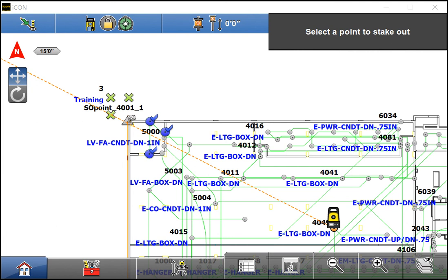Even if you don't need to send the points right away, I typically always export my points and paste them into a folder within the data folder after completing each floor. Name the folder so that you will know it contains your digital records and keep them there. If your software crashes and your files get wiped out, you will lose all stored points. You can always reload your DXFs and CSVs, but you can never restore your stored points if you don't back them up. If your software crashes, your data folder will always remain safe.